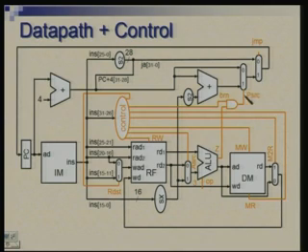Here we are doing slightly differently. We are first of all figuring out that it is a branch instruction. So, this controller will activate a signal which tells us that it is a branch instruction, and that we AND with the Z output to control this P source. So, you can see what is happening.